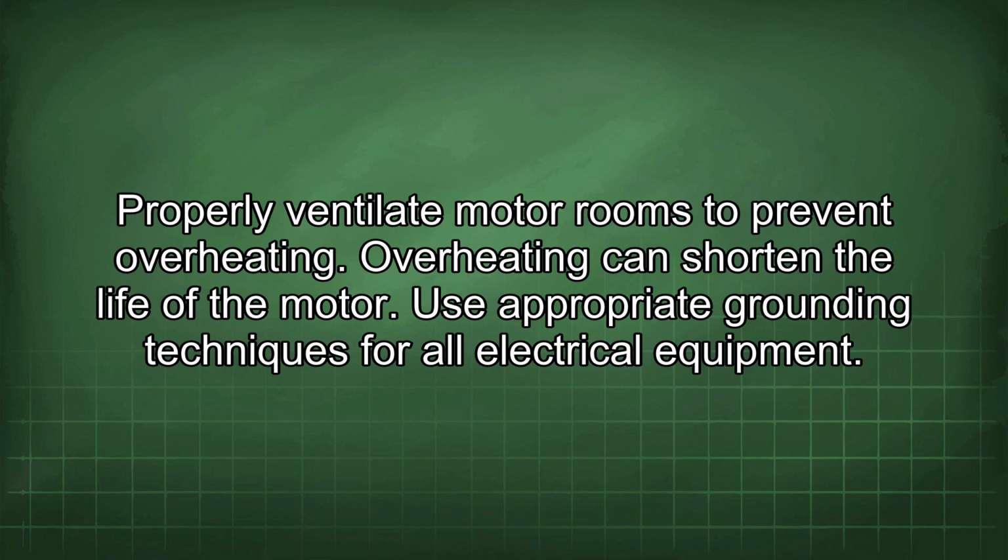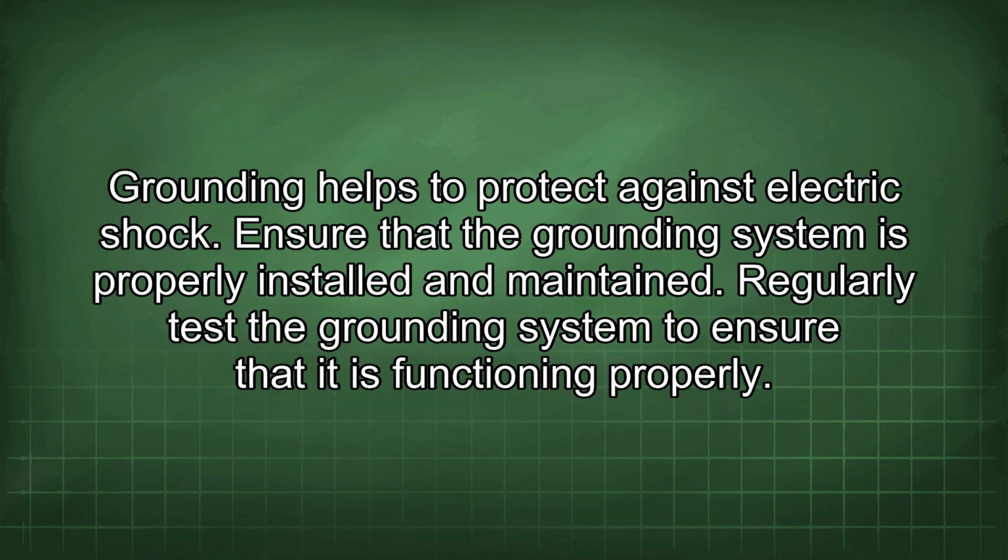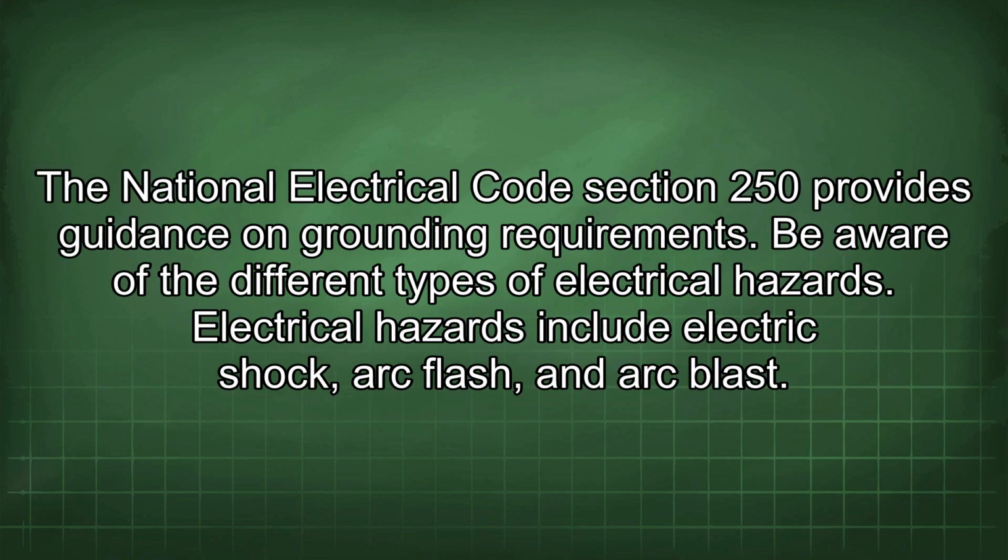Use appropriate grounding techniques for all electrical equipment. Grounding helps to protect against electric shock. Ensure that the grounding system is properly installed and maintained. Regularly test the grounding system to ensure that it is functioning properly. The National Electrical Code Section 250 provides guidance on grounding requirements.